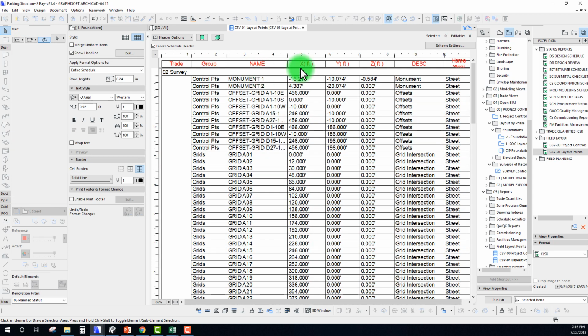With this particular library part, the format of these coordinates is, right now, decimal feet with 3 decimal places. So that's really important to note, that we want to have at least 3 decimal places. 4 I think is unnecessary, but we want to at least go to 3.